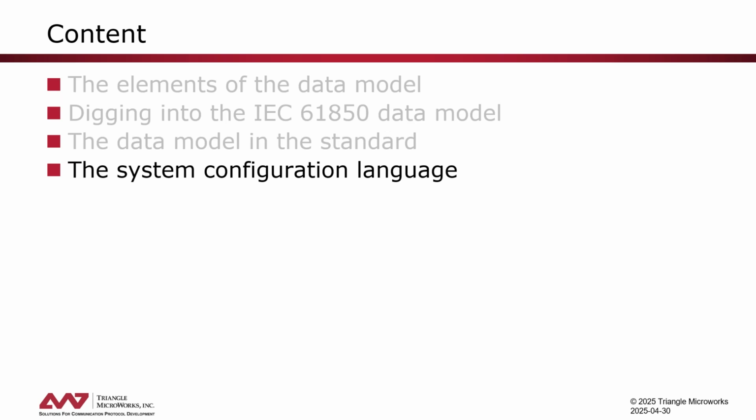Yes, that can be used as well. So typically the circuit breaker position will get into the CSWI, and the CSWI has also a position status attribute, so we can also use that. There may be subtle differences in the timestamps, and definitely when we have single phase systems, then we have individual XCBRs per phase. That's when we typically take the information from the XCBR. But yes, in principle, we also find that information in the CSWI.